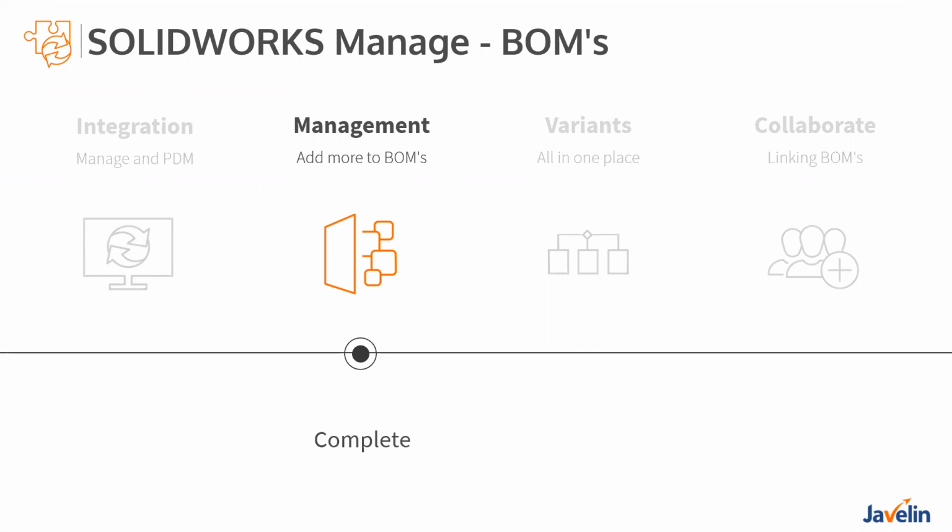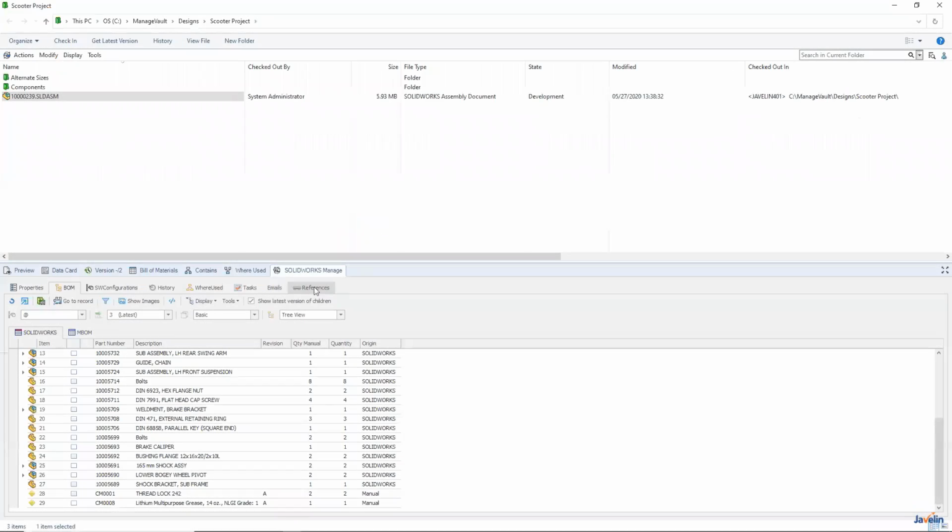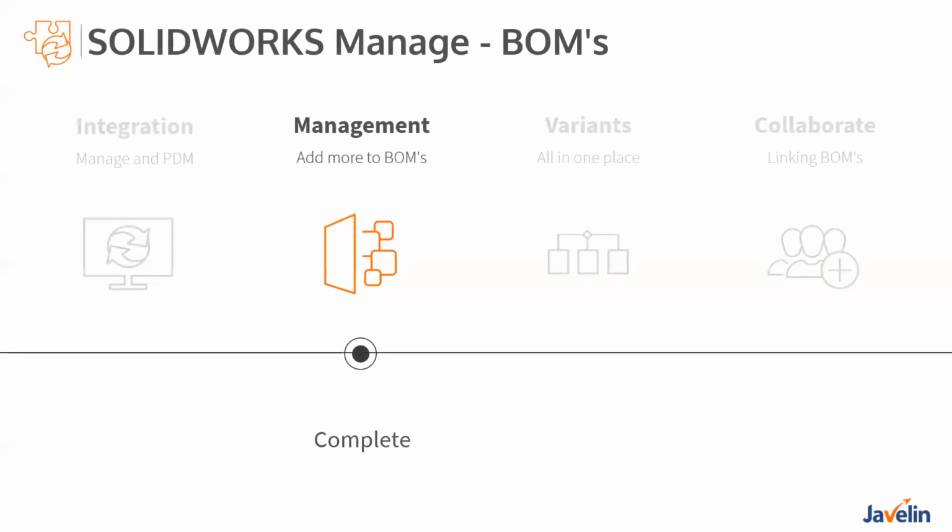The other thing as well is, it looks like I don't have it there, which is fine. We can also utilize the reporting capabilities of Manage directly inside of PDM. So if I wanted to run a report, in this case a bill of materials report or something like that, I could just do that in PDM with a quick right click, without the need to be in Manage. Manage is very powerful with reporting capabilities. It does have a built-in report builder, and we can utilize that in both the Manage and the PDM environment without having to switch back and forth.